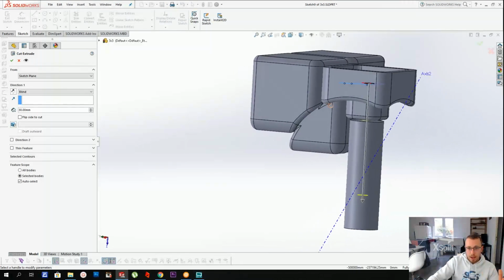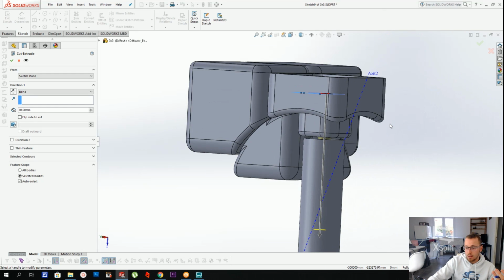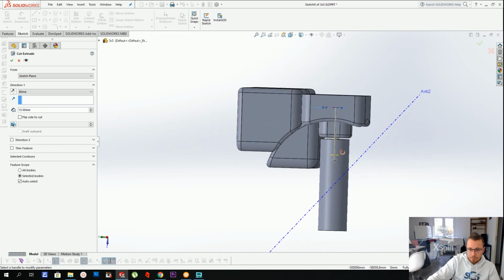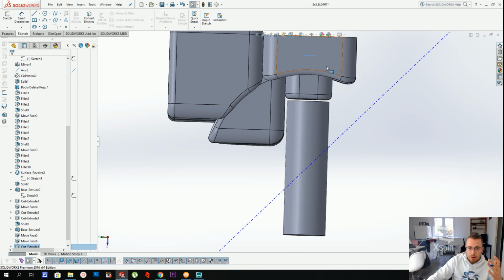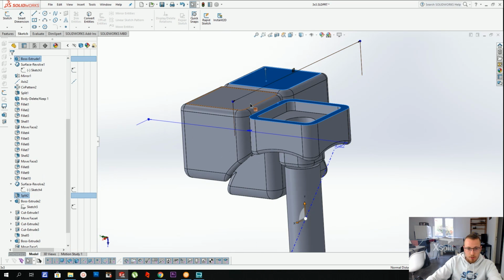And since I use M3 times 12, essentially screws that are 12 millimeters in length, I need to make a hole that's just slightly over 12 millimeters. I can use 15 because anyways, we know that we have a lot of margin here because the core center is here. So we can even go up to 18. And as long as we just don't go all the way down to the core, let's just choose 18. 18 is fine. And now, let's see what the core looks like at this point.